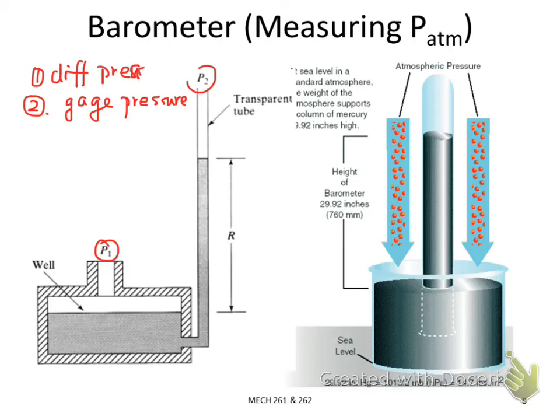But there is one more type of pressure sensor we know, the absolute pressure sensor. Actually, you can also convert a U-shape, tube-based manometer into an absolute pressure sensor. We call it a barometer as well. A barometer is a pressure sensor which is used to measure atmosphere pressure.